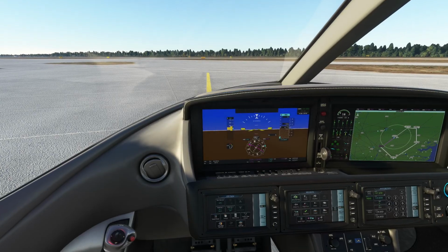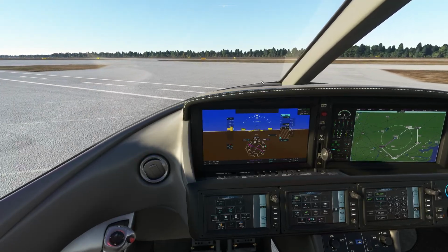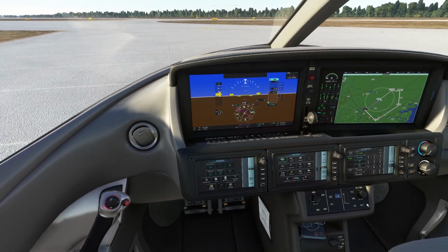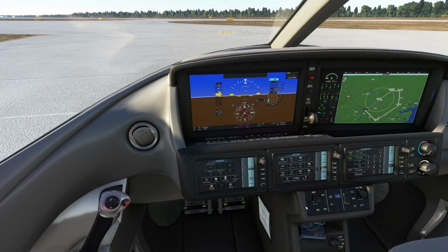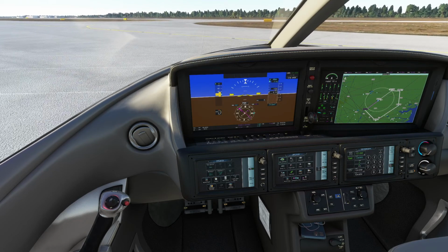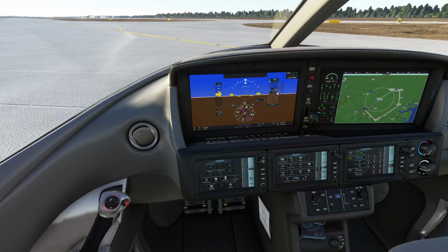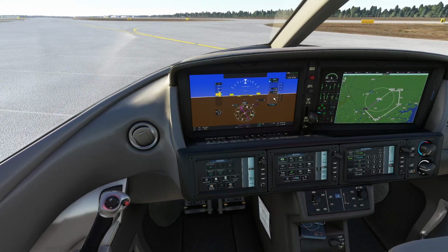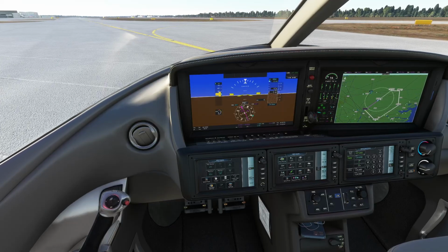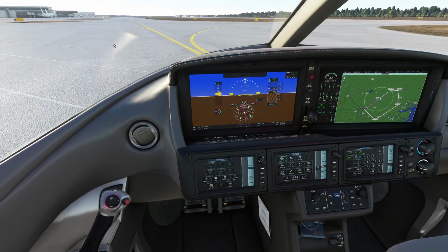Okay, so let's go and roll out to the runway. As we roll out to the runway, let's have a think about the altitude we're going to be flying at. So to set that, you'll see the target altitude is at the top of the altitude ribbon on the primary flight display. So if you roll the altitude knob, this is the master control panel for the autopilot, by the way. So if you roll the altitude, you'll see the number changing up here. So we'll go and set it for 5,000 feet. There we go, 5,000 feet. We're going to press B as well to calibrate the altimeter, so you can see the numbers changing here. So we're now showing an accurate altitude above sea level, at ground level at the airport. Okay, so we've set that. We'll worry about the rest once we're in the air.